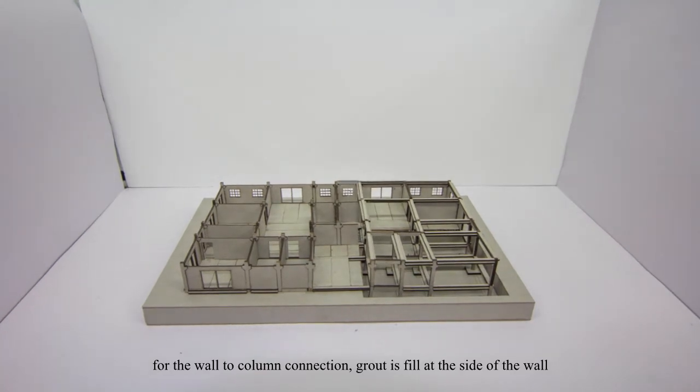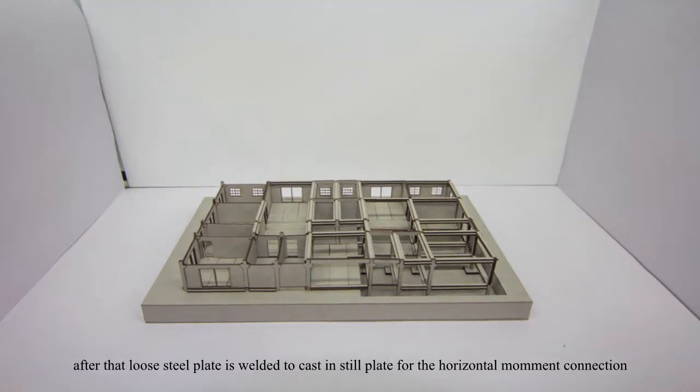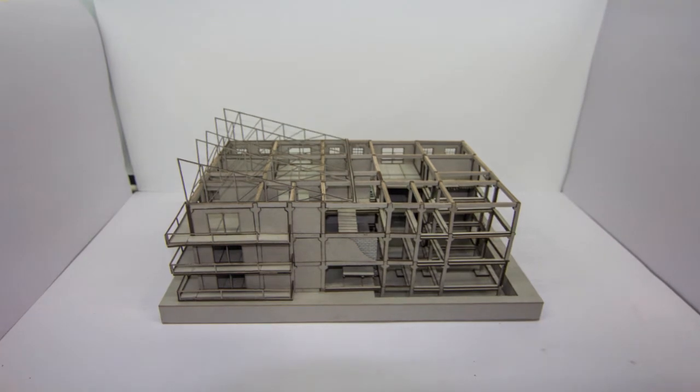For the wall-to-column connection, grout is filled at the side of the wall. After that, loose fill plate is welded to the cast-in steel plate for the horizontal moment connection.